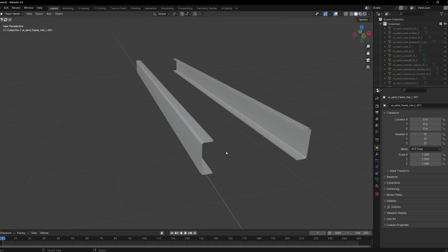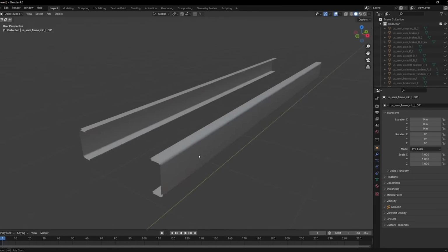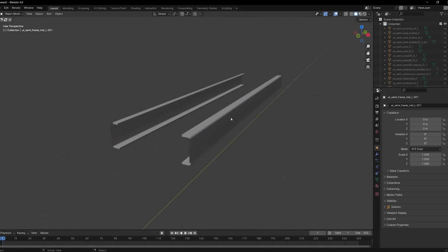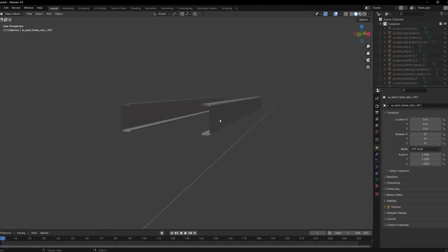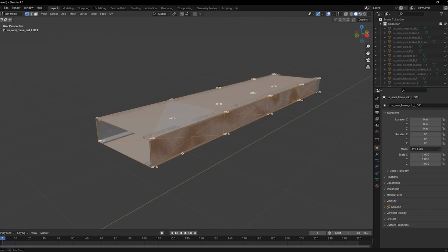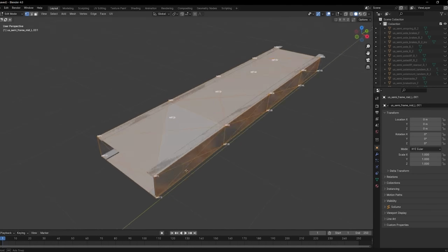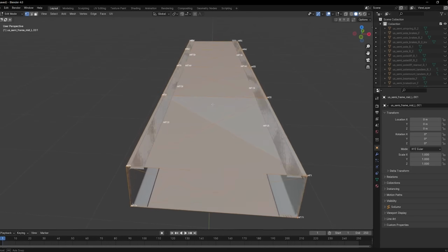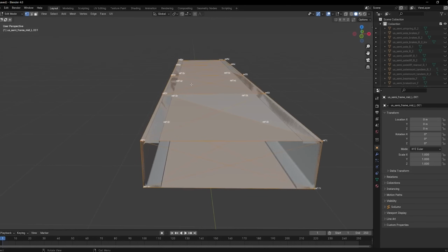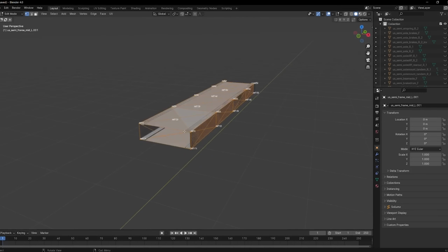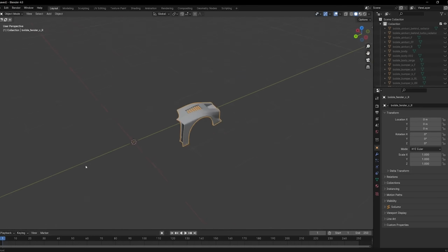Actually, let me explain it to you this way. This is the frame of the US Semi, the new updated version of it. But this is not how the collisions work. If you look at this, you would think that it would have long strength this way, but instead what they have to do is set up this much more rudimentary style collision mesh. And it's not even just that thick, it has to be conjoined, otherwise it'll be too complicated, and twisting and torsion, all that sort of stuff isn't gonna act the way you want it to. So why not actually make it like that?